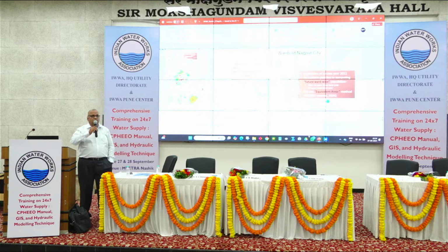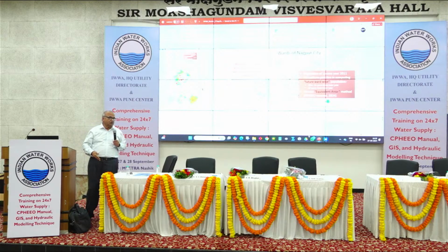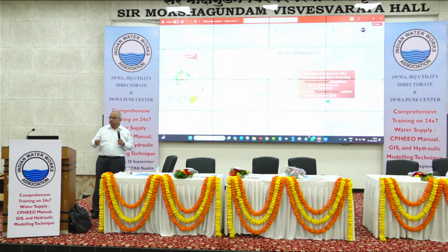First of all, you have the ward boundaries GIS layer, and you have the census data of those wards. For medium-sized cities also, census data is available, say about 2011 data. You have to find out the population forecast of this ward. Then only, using another method, we can allot this data. But first of all, now...